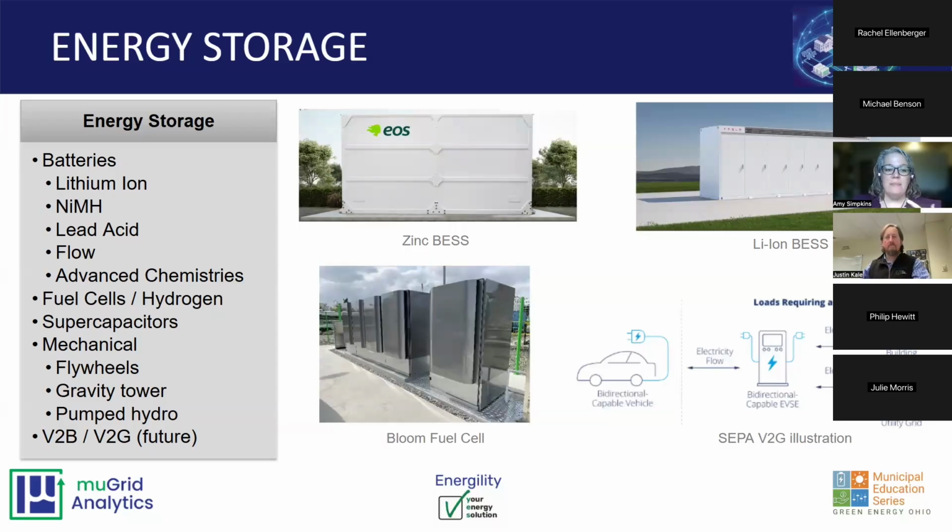Fuel cells have a similar look to the battery. Batteries and fuel cells are housed outside on a concrete pad. They look cabinetized. These cabinets are NEMA 3R rated, which means they're rated for all sorts of weather. Often all of these types of cabinets that are designed to sit outside will have their own HVAC system because batteries like to be very stable in temperature.